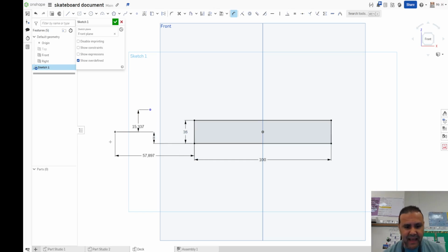And that puts me at our first location. Now, this one right here is going to be dimensioned from the topmost left corner. And we're going to put this at 50.442 millimeters. Now, I'm already in millimeters, so I don't have to change that, but there you go. So now you have this right here in this kind of design.